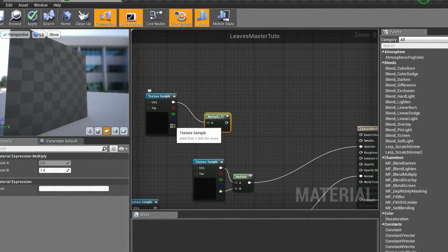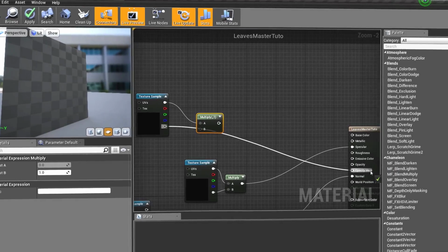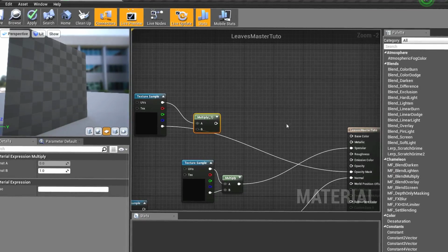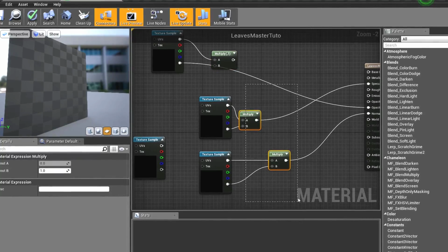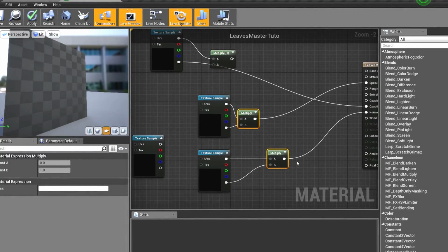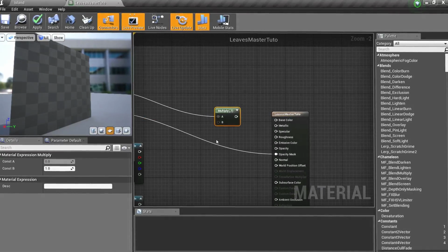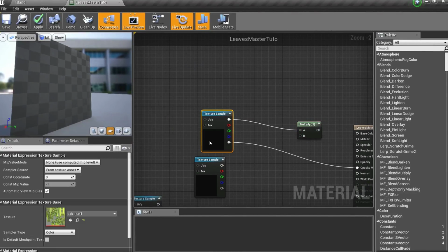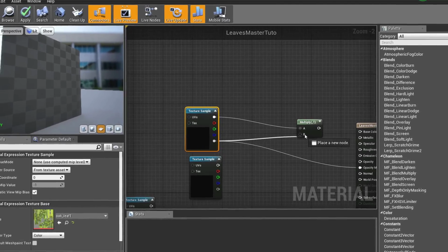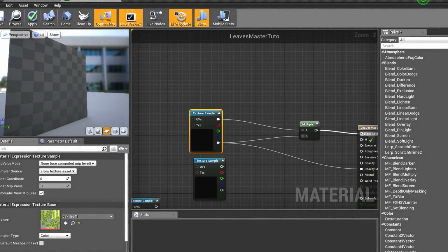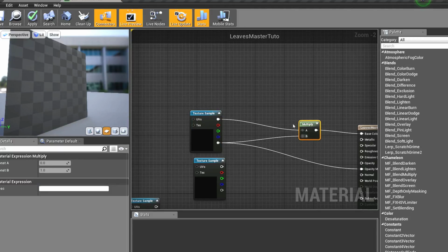And how do we prevent that? Go ahead and put this into the opacity mask. Either you can multiply these or you could just use the opacity mask, which I'm gonna do. The opacity mask will basically tell it where to process. Actually, we don't need this multiplier anymore, do we? I just held control and left click and dragged it in here.